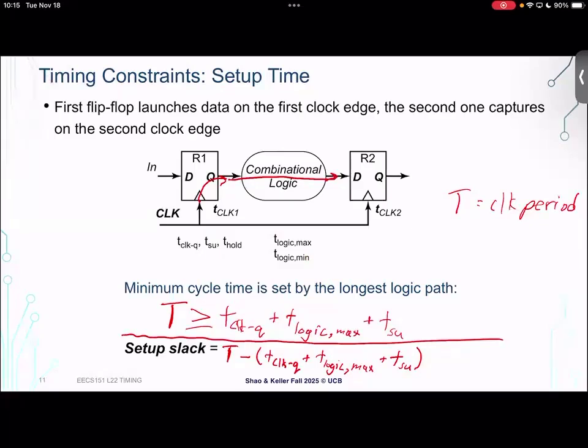Yeah. So in both ASIC or FPGA flows, the tool is doing a version of this, and when it generates your synthesis reports, there will be some sort of timing report that you can look at. It'll list some timing paths, and at the bottom of each path, it'll say slack, and it'll either say met or violated in big letters, right? If slack is met, that means there's positive slack, there's extra. If slack is violated, that means the slack is negative, and that means you're not meeting this constraint.